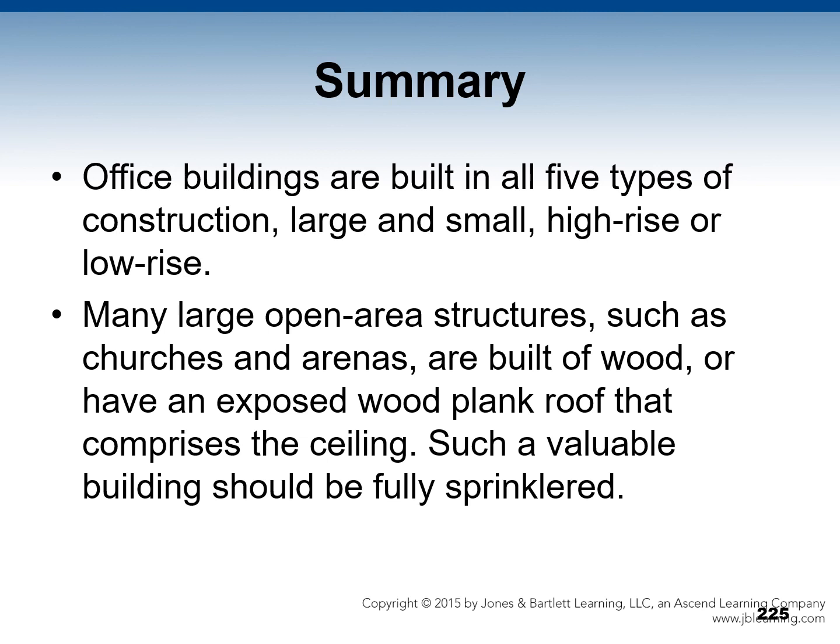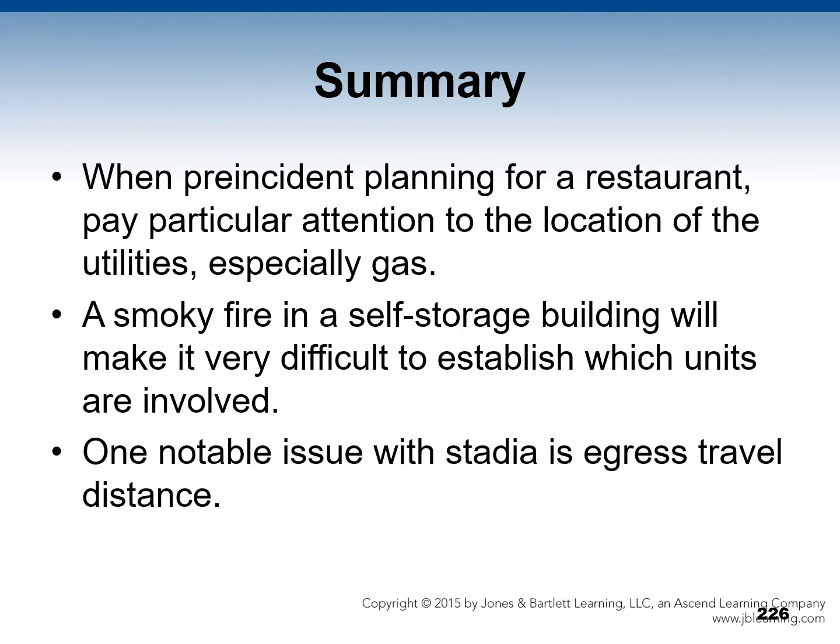Many large open area structures such as churches and arenas are built of wood or have an exposed wood plank roof that compromises the ceiling. Such a valuable building should be fully sprinklered. We discussed restaurants, and when pre-incident planning for a restaurant, pay particular attention to the location of the utilities, especially gas. In self-storage buildings, we talked about how a smoky fire in a self-storage building will make it very difficult to establish which specific units are involved.